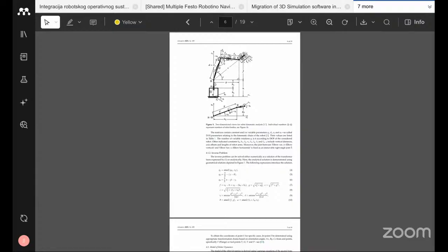Then the vertical height difference is F. Horizontal radial distance, effective length, shoulder to target distance, triangle length, triangle angle, target, elbow angle, calculation sequence. So the calculation sequence will be the target reference point E, then after that Q1, then H, F, G, E, C, V, omega. After that, Q1, Q2, Q3, Q4, Q5, Q6, then finally calculating the TCP orientation.